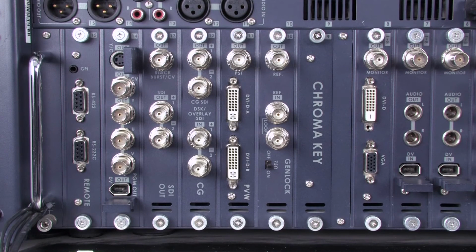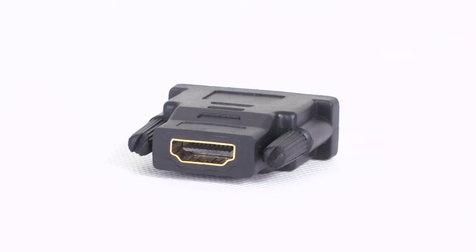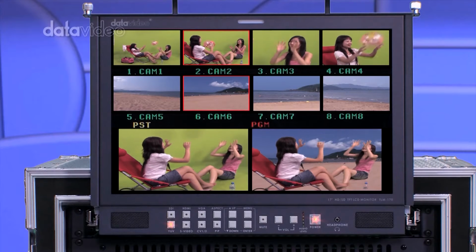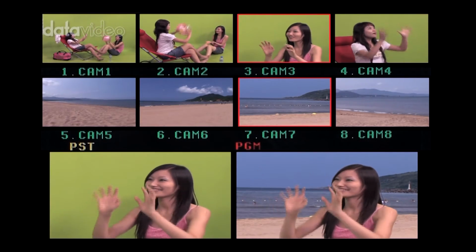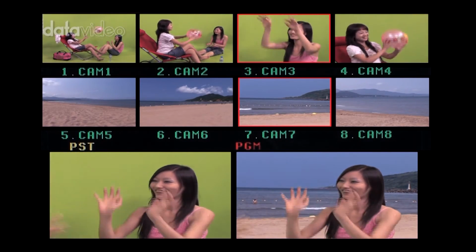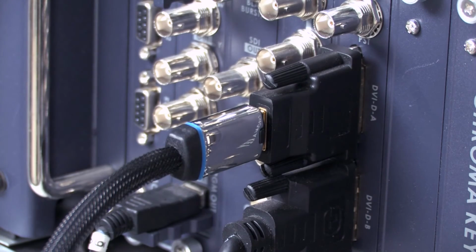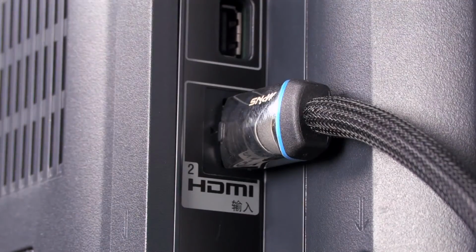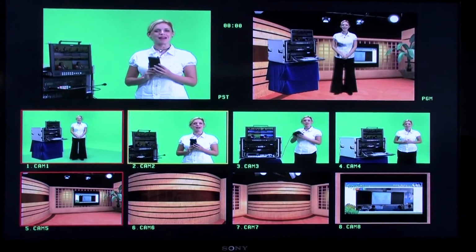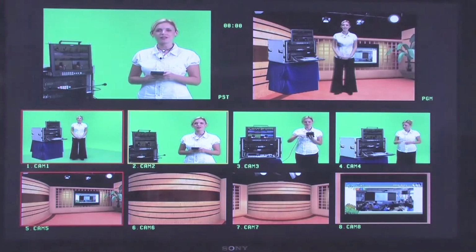If you buy the MS-900 and use the DVI multi-image output card, you will see that the interface from top to bottom has 2 similar DVI-D multi-image preview output interfaces, one for preview and the other to be linked to a DVI-D to HDMI cable to connect to the TLM170 for monitoring of 10 videos at 1080p. Both DVI output functions are the same, so you can use the top DVI output converter to HDMI to output to high-definition 32-inch and above display panels to achieve bigger dimensions of 10 video viewing output.